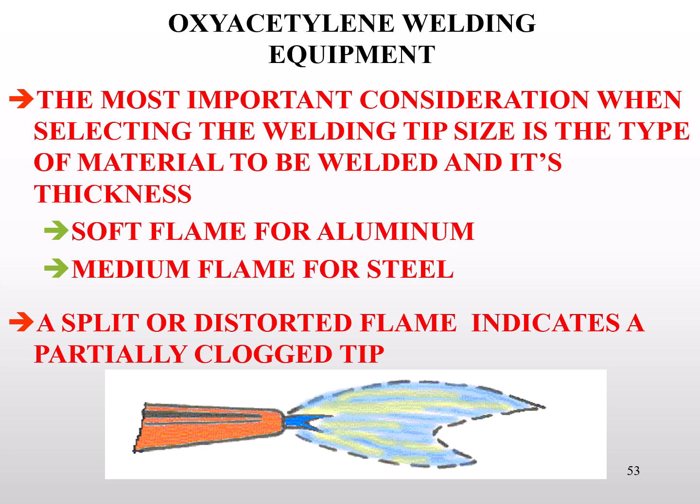There's also a couple of terms dealing with flame that need to be understood. There are soft flames, medium flames, and harsh flames. When you're describing a flame using those terms, what you're actually talking about is how much gas pressure is being used to create the flame. So a soft flame has a low pressure coming to the tip, then medium, and then harsh, because we're using higher and higher pressures as we go along.